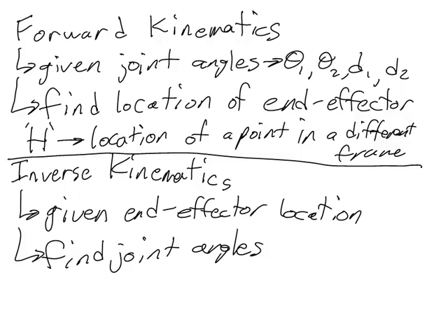Inverse kinematics ends up being much more useful to us as robotics engineers because typically this is the kind of problem that we need to do with our robots. For example, we might know that we need the end effector, if it's, say, a gripper, to become located where an object is located that we want to pick up. In order to place the end effector in our desired location, we need to figure out what joint angles will place the end effector in that location. And that kind of a problem is inverse kinematics.